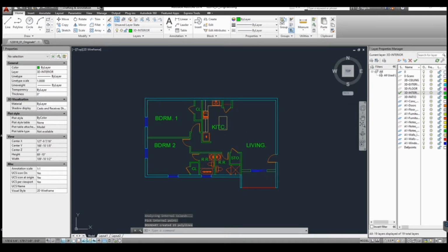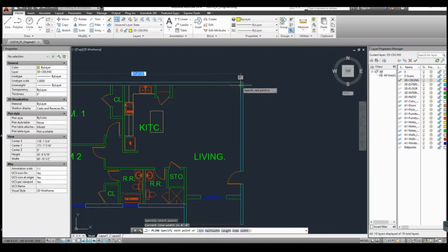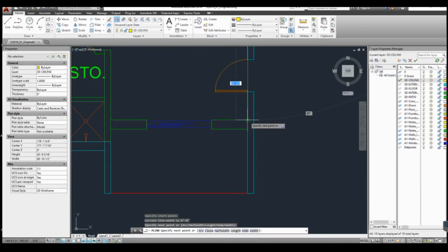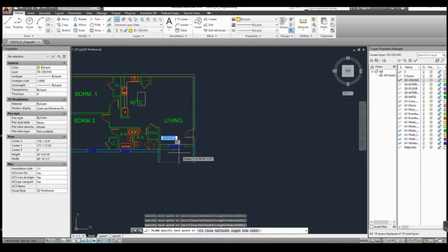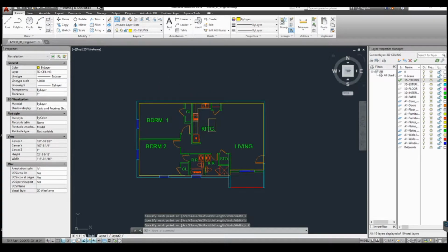So now we'll go over to the 3D ceiling layer, and then we'll select polyline. We're going to go ahead and draw this polyline in here now. The 3D ceiling is the active layer, so it is drawing a polyline for our ceiling in exactly the way that it's going to be. Once we pull it over there, I'm going to type C to close, as we know where that last point is, and we get a good close.